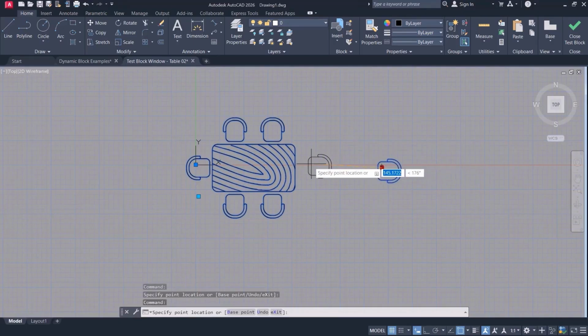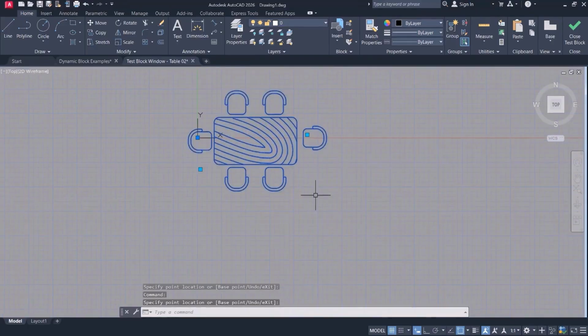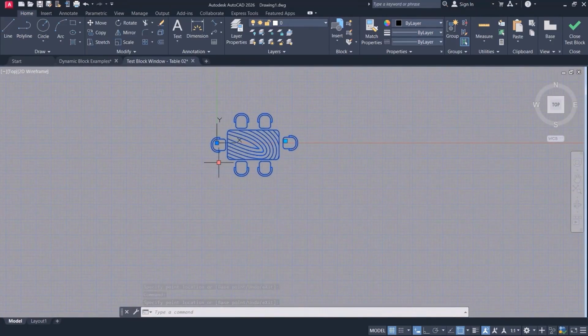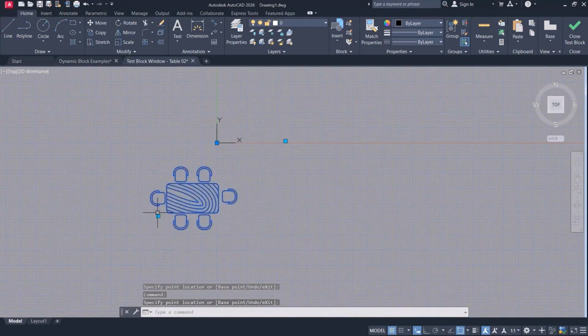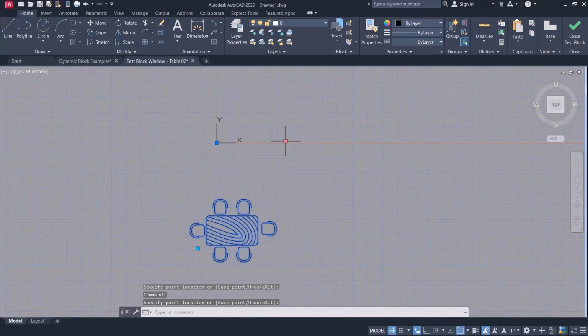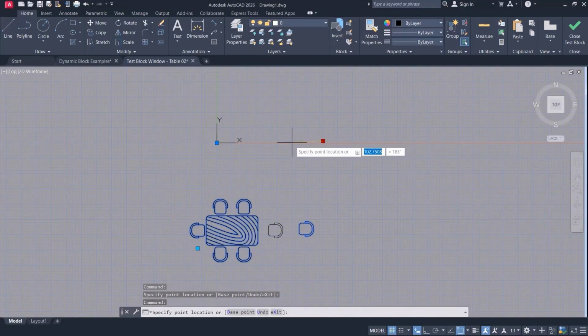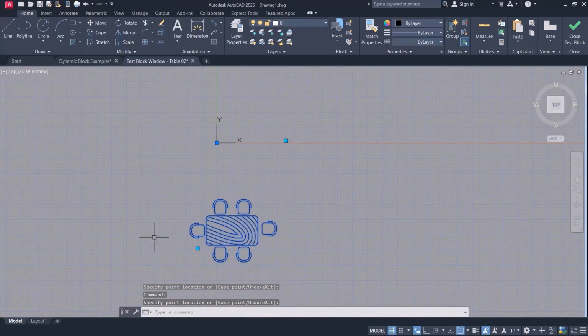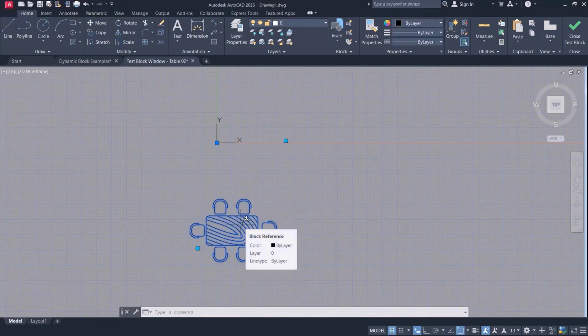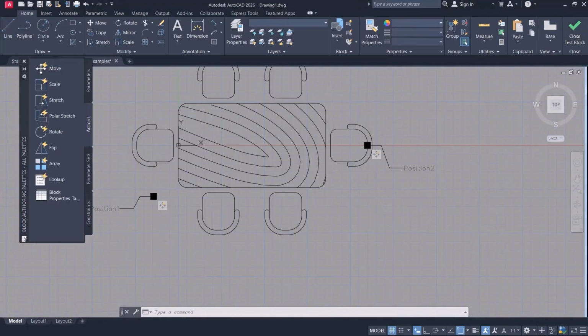Now here's a crucial point that requires attention. When I change the whole object, the move grip related to this chair gets separated. Why is that? Because the first time I defined this point, I said let this whole object move, or this move parameter. But the new one I made wasn't in my selection, so that point didn't exist either. I have to say, bring this one too. Let it move. What do I do?